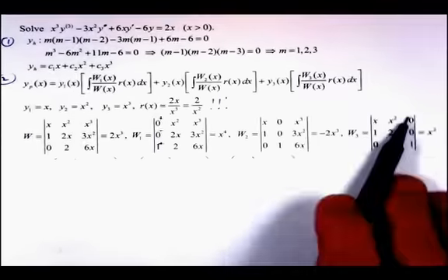We're assuming that the material itself is homogeneous, that is, it has the same density and consistency and material all the way through. So homogeneous in this sense just means the same. Certainly not all beams will be the same all the way through. If there was some sort of fault in the beam, then this model wouldn't necessarily be a good model of that system. Okay. So it could be steel, it could be wood, and it's a uniform cross-section. It's the same cross-section all the way along here. It doesn't have to be rectangular, but if it was circular, it was the same circular cross-section all the way along there, as long as it's uniform.